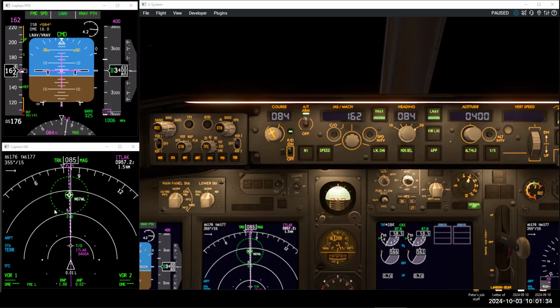So some carriers teach to draw a 2 nautical mile circle around the final descent point. And I think that's a great idea to trigger us at that point to the gear down, flaps 15, speed brakes armed, and then make sure we're in VNAV path, make sure the minimum has been set, and round it up, in our case, to 400 feet, and our RNP AMP check, and then configure the landing flap.